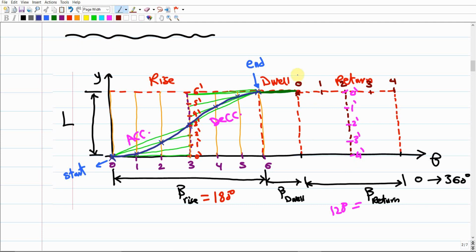So you have to define where the start point is located. This is our start point for the return motion, and this point is gonna be our end point for the return motion, right? So you're just gonna connect the start points with the nearest marks. We do have here the middle mark, which is 2. So you're just going to connect 0 dash to the 0, 1 dash to the 1, to the 0, to the start point, right? Then the 2 dash will be connected to the start point.